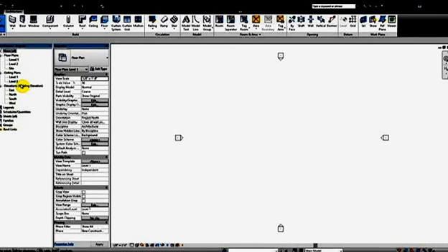If you opened a none template, there may not be any views visible when you expand the views folder. When you create new views, they'll be listed here, and they'll be sorted depending on what type of view they are. And you can get into more micro level sorting of them based off of the use. Say we wanted an interior elevation, we could do that. I'm not going to cover that now. That'll be a later tutorial, but you can really customize how the stuff is sorted in this browser.